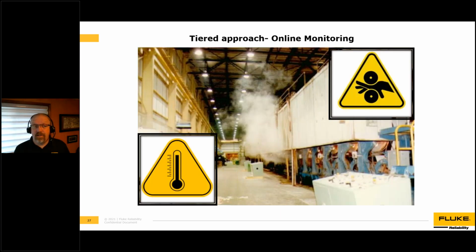In this picture, we see the tending side of a paper machine dryer, and this is where the operators spend most of their time. The motors and the gear sides are on the other side. They're on the drive side. And vibration data is largely collected from the drive side, which is a terrible place to have to physically collect data. It's very hot, and with exposed dryer cans and rotating shafts, it can be a little dangerous. So that makes it the optimal application for an online condition monitoring system.